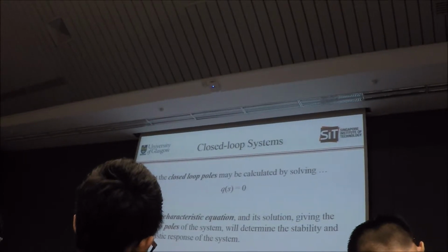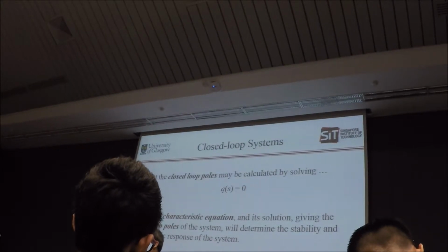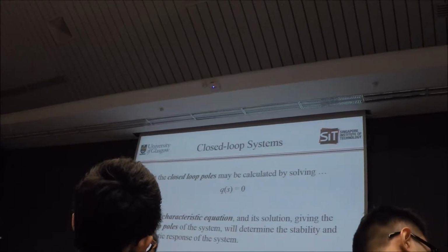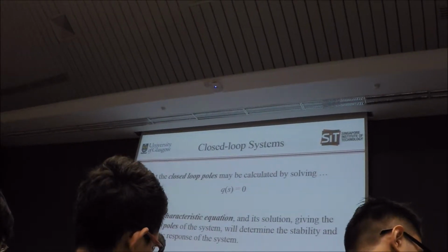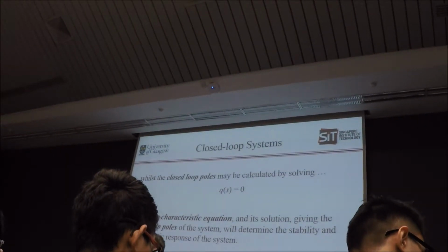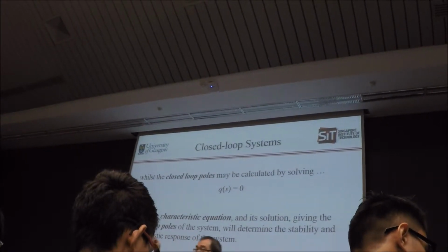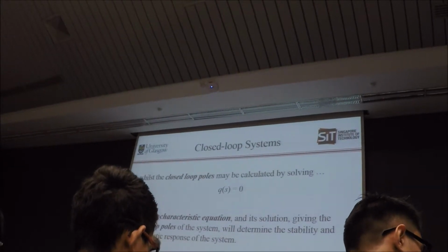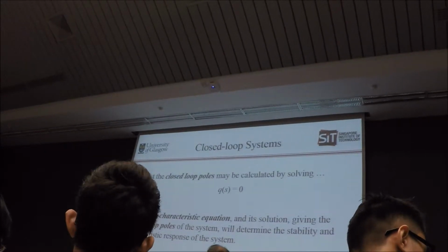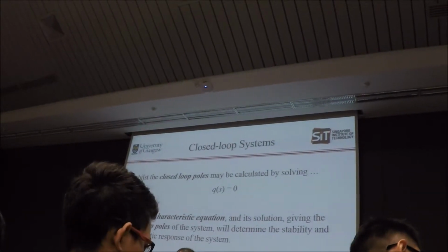Whether your closed loop system is stable or unstable is primarily determined by the pole location of your closed loop system. If the poles are in the left half plane, no problem, the closed loop system will be stable. The moment the poles move to the right half plane, your closed loop system is unstable. That's what we discussed before using your PID controller, or your PI controller. We did mention that because both increase your system order by 1, they run into a possibility of instability.